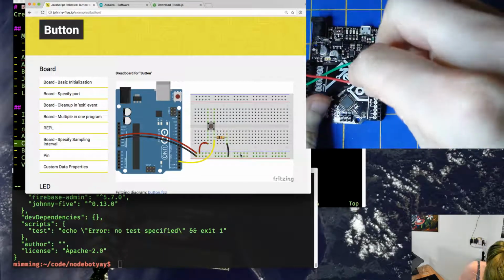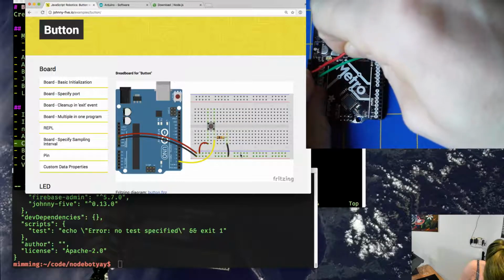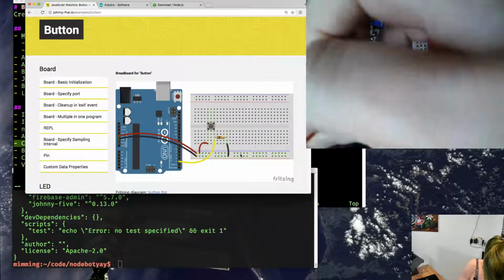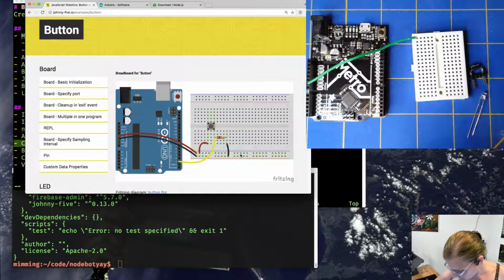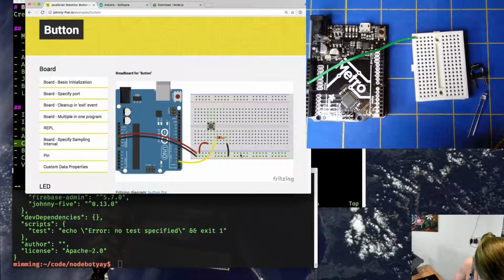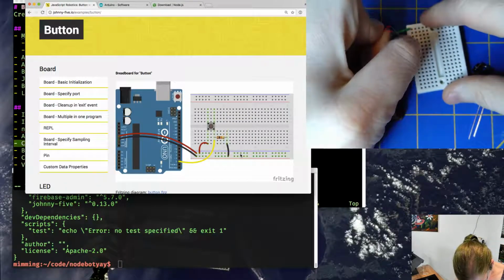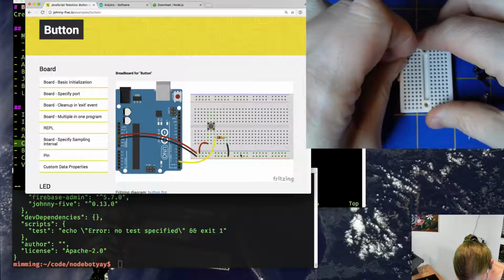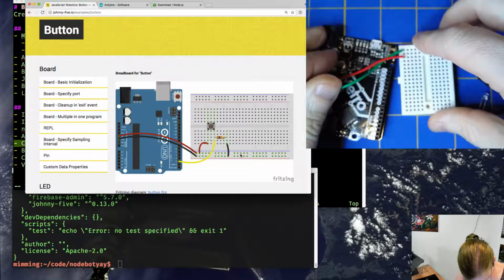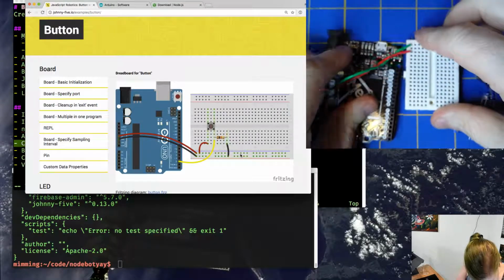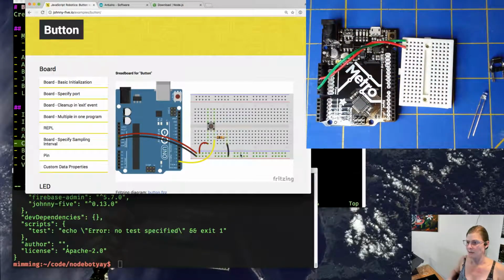Then we're going to take the 5 volt line. We're going to copy that to my little pin, and my thing is starting to wear out. Get one with slightly longer leads. Go to the 5 volt pin, and we'll copy that somewhere else. So I'll copy it a couple lines below on the breadboard, to reduce the chance that they cross paths and short out, because that would be sad. If they touch, things will stop working.